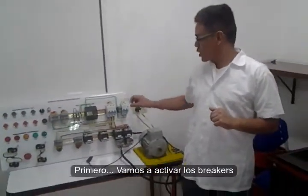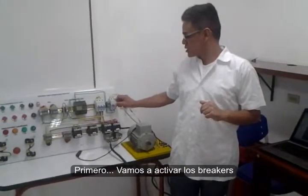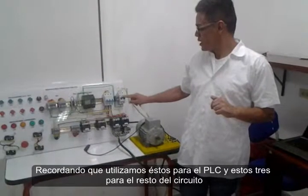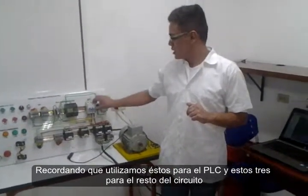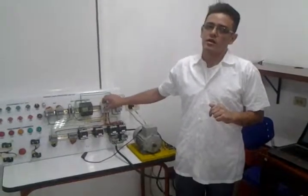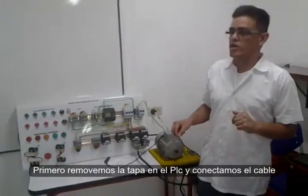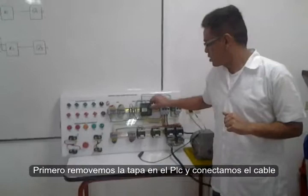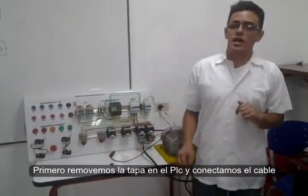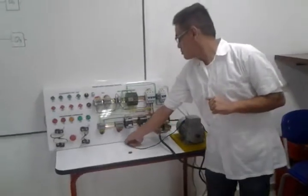Alright, first we are going to activate the breakers. So we remember that we are using these breakers for the PLC and these three ones for the rest of the circuit. Alright, first we remove the port cover. We have to remove the port cover of the PLC and connect the cable.